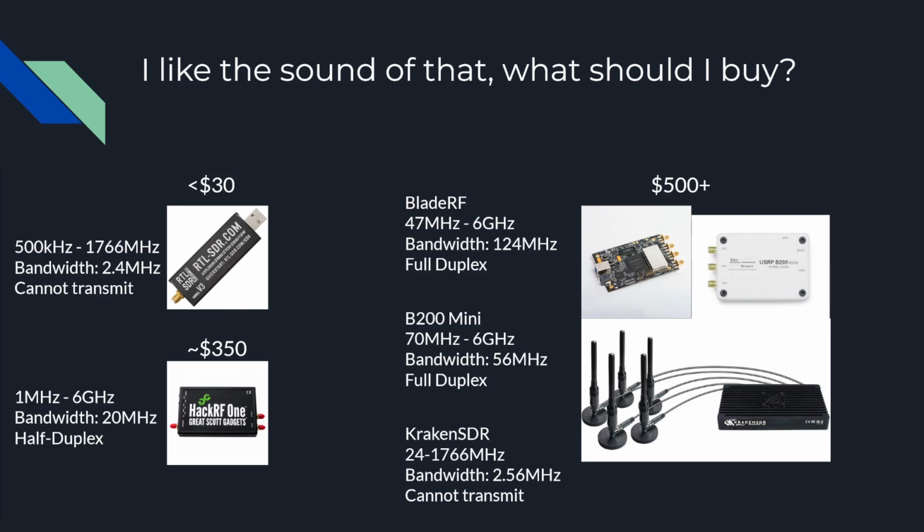But the hardware can get very complex, depending on the radios, and even just hardware radios can be pretty complex too. Simple ham radios are really cool to look at from an electrical design, but the Kraken SDR there is very complex, because even though it's 8 of these RTL SDRs in tandem, they have a couple of real-time clock components that all work together to keep it all in sync. And then that's all patched up, and then they have the antennas to direction hunt.